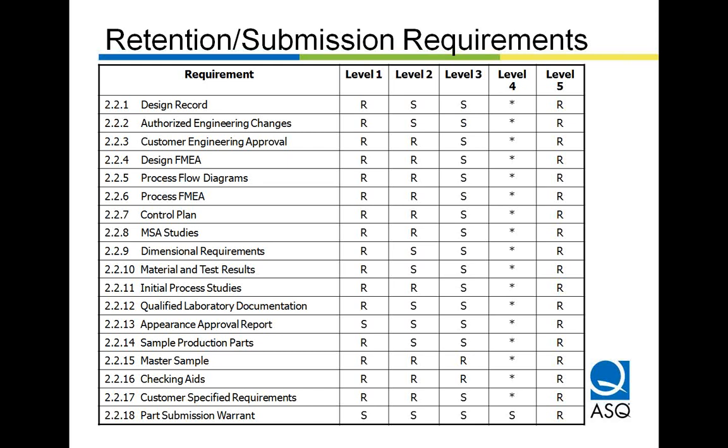The SPC manual and the PPAP manual suggest that PPK is appropriate for those cases where you have not demonstrated process stability.